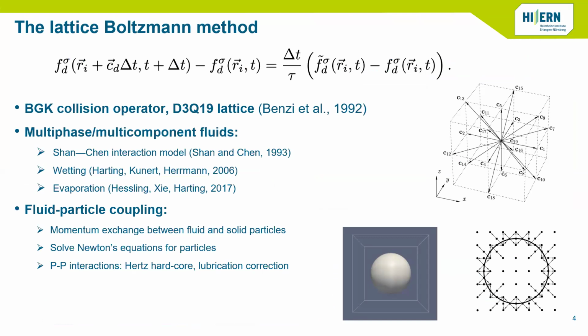And we couple the fluid with particles, just following the approach outlined. So there's momentum exchange between fluid and solid particles. We solve Newton equations for those particles. And we also can implement the particle-particle interactions straightforwardly in this model.